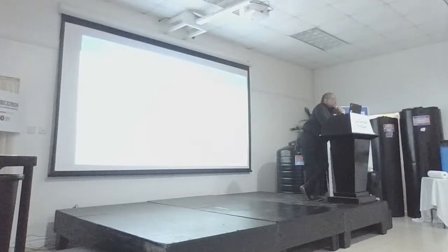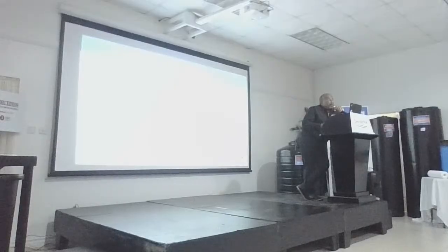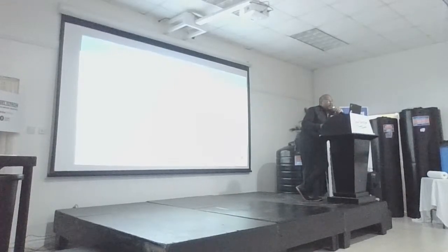Secondary treatment. The secondary treatment is an additional phase where the wastewater goes through further treatment. This reduces odors and other content from the septic tank, so the secondary treatment could be a soakaway or a leach field, or it could be a prefabricated tank that you attach if you have challenges in a particular area where you can't have a soakaway or a leach field. But the soakaways and the digesters, because we make a product called a digester, which I'll come to, facilitate further breakdown of the wastewater and the organic matter and removal of contaminants.